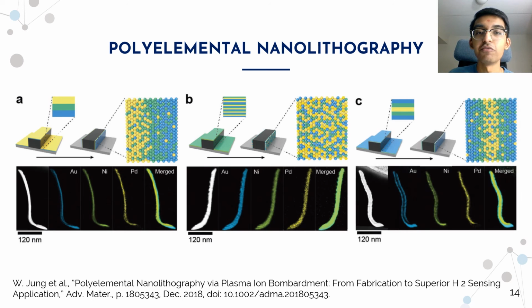Lastly, the core shell inner structure, which they made by depositing 5 layers on the substrate, is shown here. They deposited these layers in the order of gold, nickel, palladium, nickel, and gold, and the resultant nanostructure exhibited this core shell structure with the same sequence of deposited metal layers. In general, they showed that multi-metallic nanostructures with tunable mixed structures could be developed.